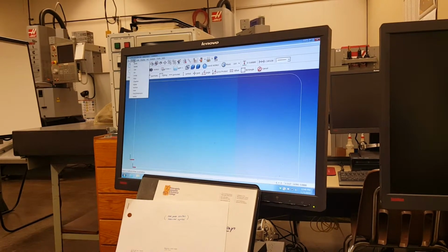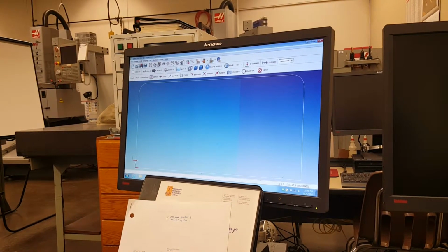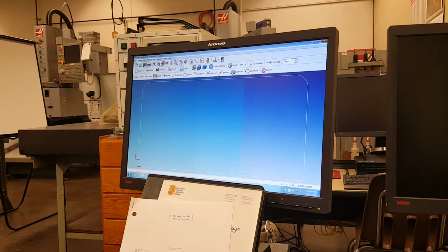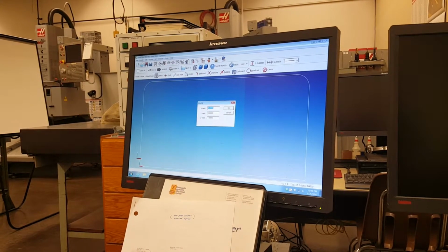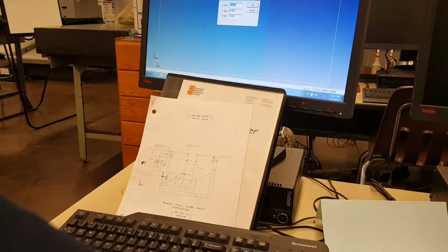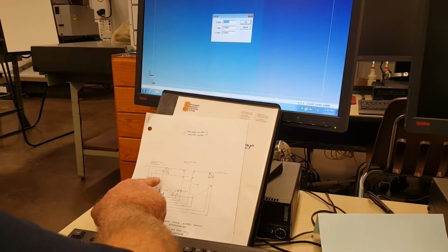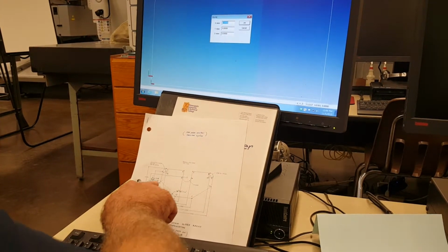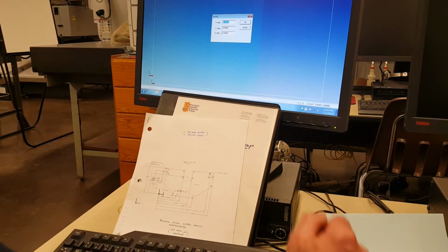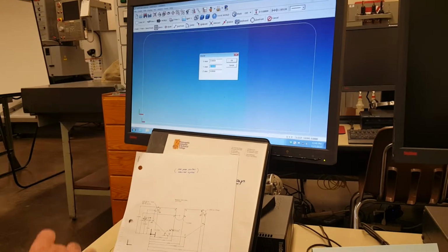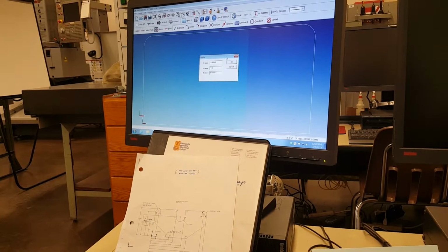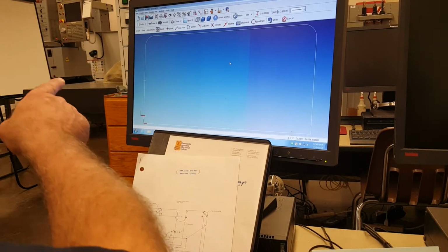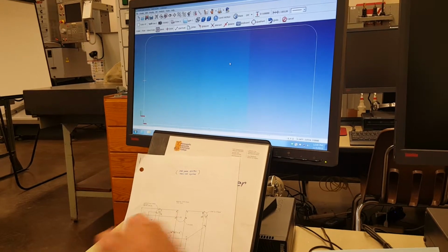And actually I'm going to create a point, use keyboard, and I'm going to figure out where that point is. So my X value is 0. Okay, but my Y value is 1.5. So I'm going to just tab down, 1.5 and hit OK. That's where the start of that angle line comes.